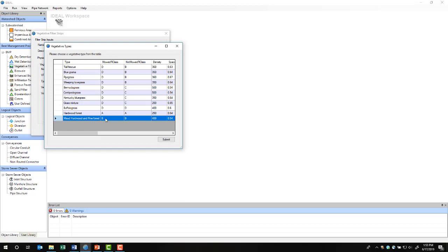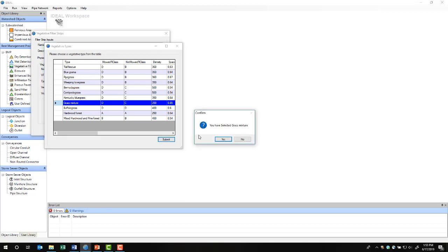If you choose to model a forested area as a VFS BMP, there are a couple of key points to keep in mind. The first is that a filter strip relies on sheet flow for trapping, and the uneven ground, wide tree trunks, and roots tend to channelize flow. A forested VFS will be relying primarily on leaf litter to filter runoff and capture pollutants, but that leaf litter can be washed away if too much runoff is artificially directed toward it. Designers need to be sensitive to these limitations when modeling a forested VFS and should not direct too much flow to them in order to avoid washing away the ground cover and exposing bare soil.